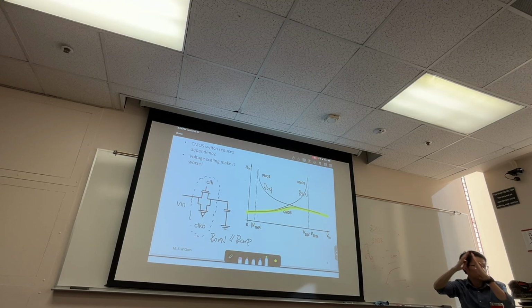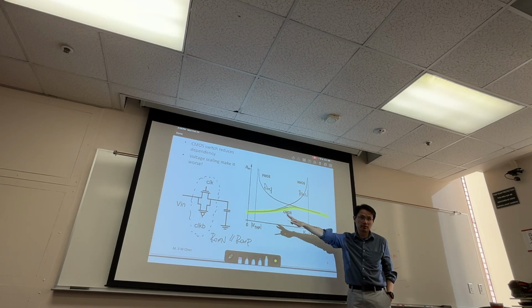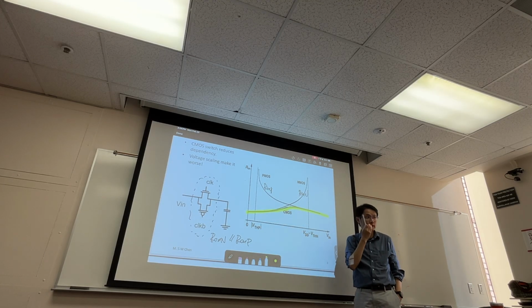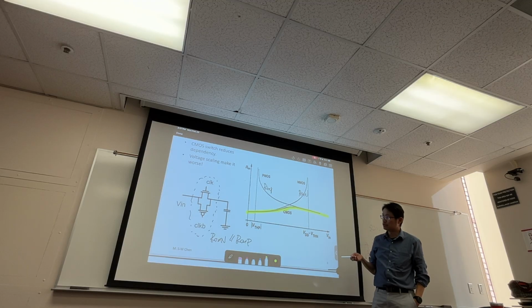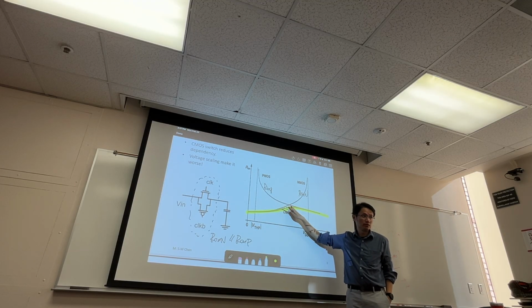That's where the two kind of combine, and it depends on the threshold voltage and your VDD. So you do need to simulate; the transmission gate is not just going to solve all your problems. Depending on the technology, you want to simulate the whole thing.